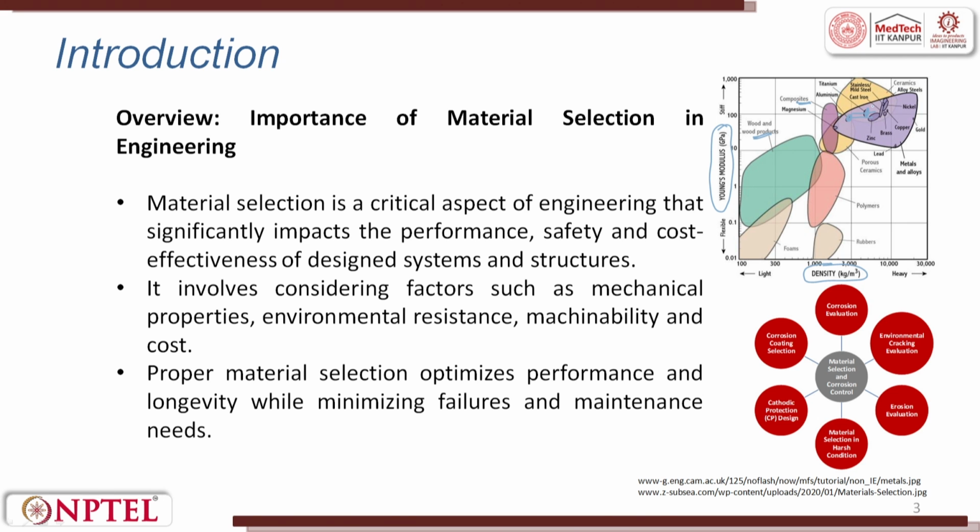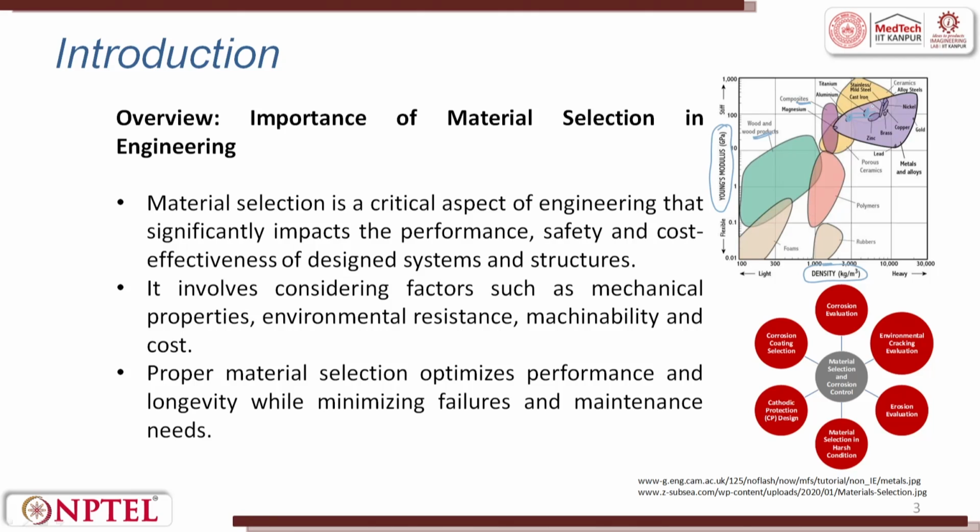Second thing is you will see the longevity of the part. Third one, when you talk about all these moving vehicles, let it be car, let it be plane, we always look at what is the mileage. So, if you are looking for mileage, magnesium will be chosen as against titanium. So, in this Ashby curve, he has plotted several spectrum of materials.